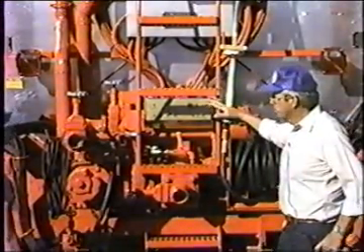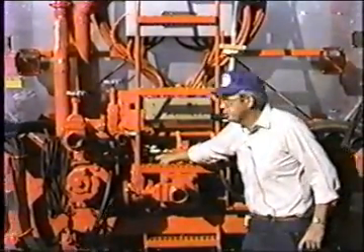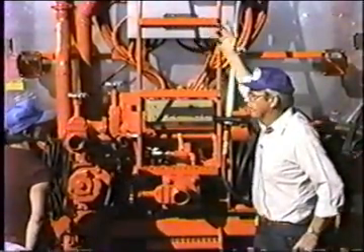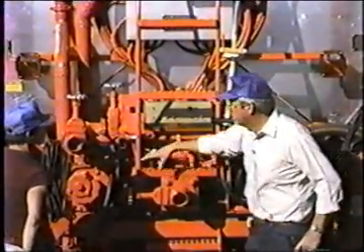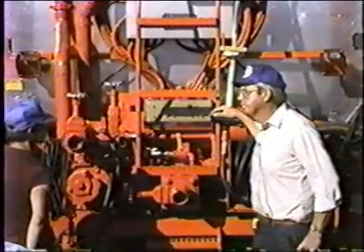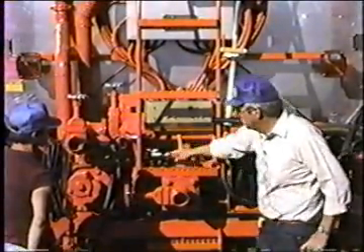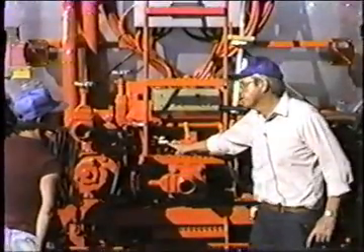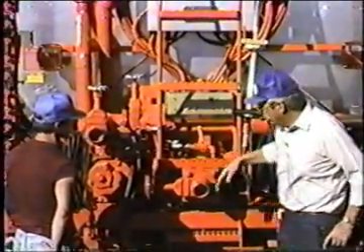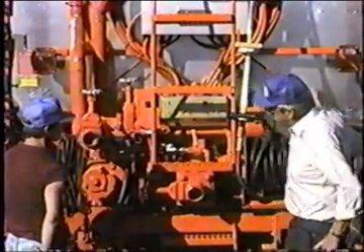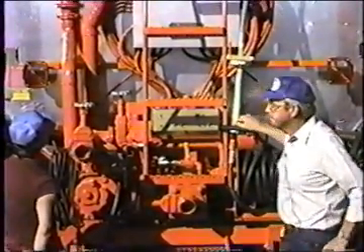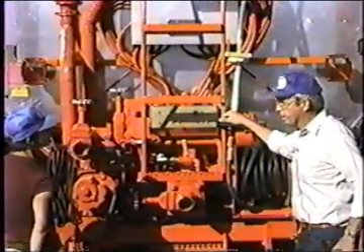If that master switch were turned on, it would short circuit through the equalizer valve, go right through the bypass valve into the tank, and nothing is cleaned out except for the strainers, the pump, and the bypass valve. Okay, so this is a good time to look at that and be sure that rod is extended on the equalizer valve cylinder. Okay, we're pulling air in through the entire circulation path, blowing the liquid back into the tank. It'll blow 80% of it back into it.